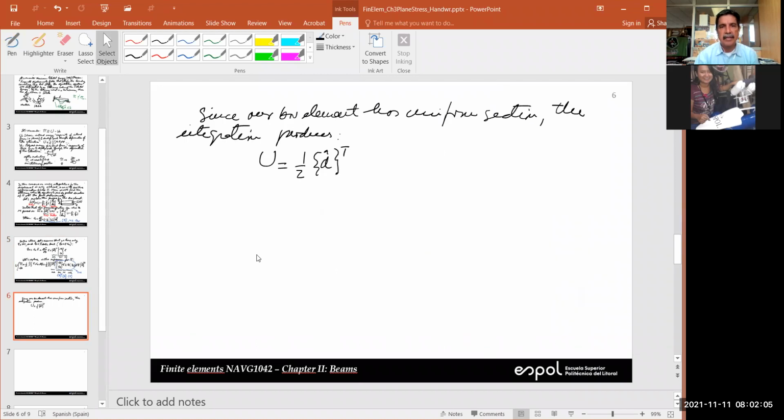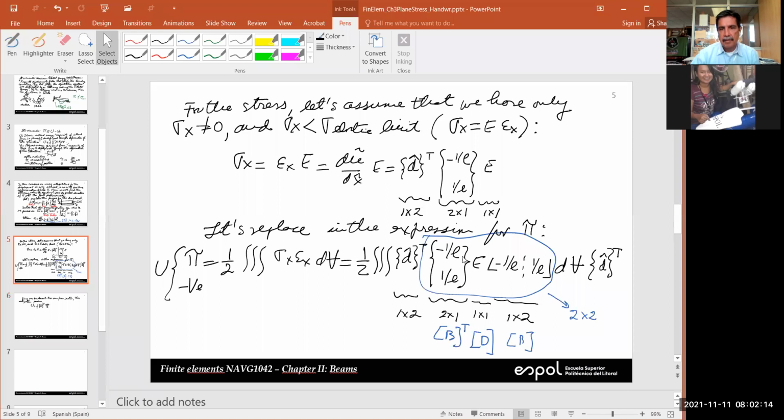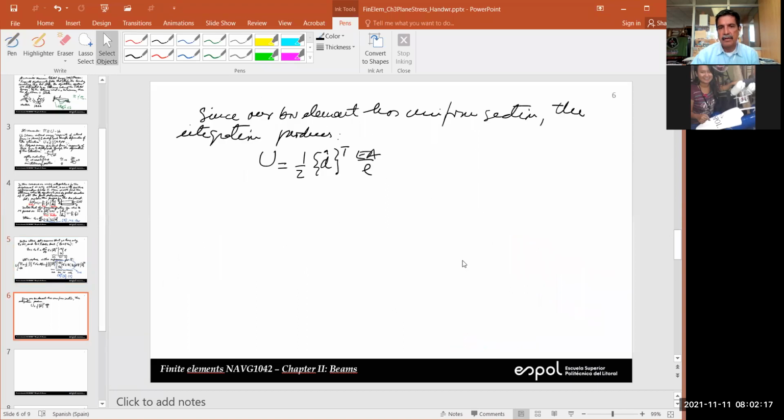So we're going to say that that's equal to EA over L. And then from this vector, we're going to say that this is equal to minus 1, 1, minus 1, 1. Okay, so the integration is AL divided by L squared. So we cancel 1L. So that's what we have.